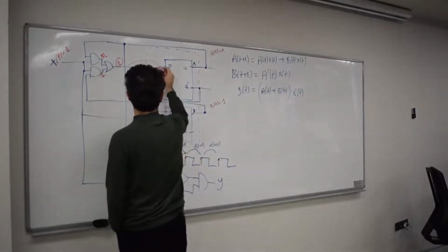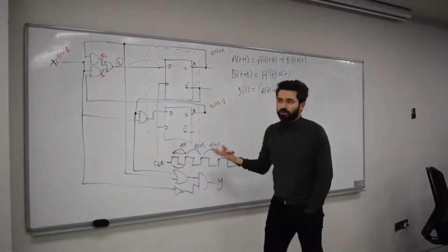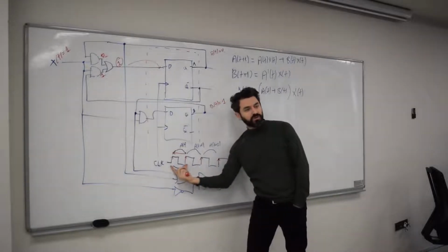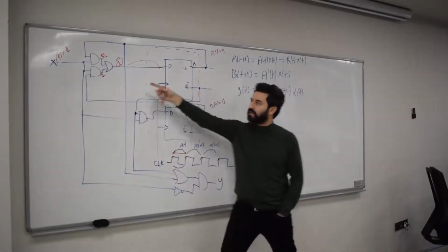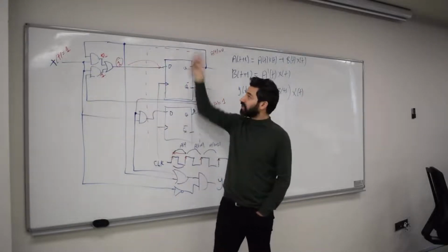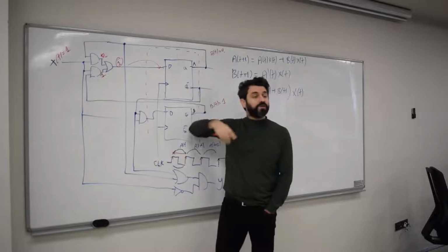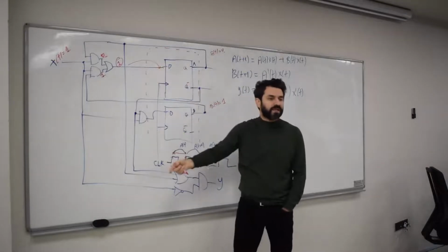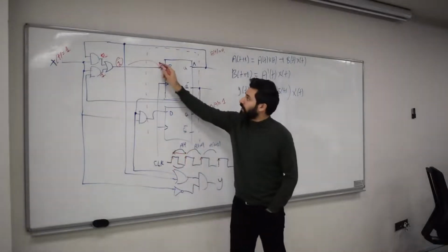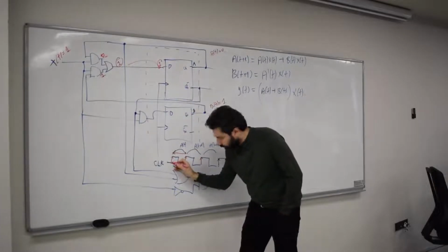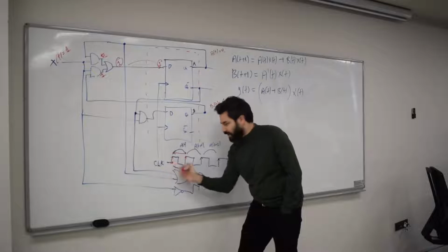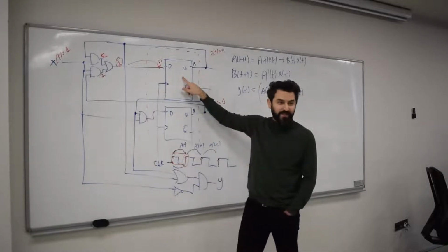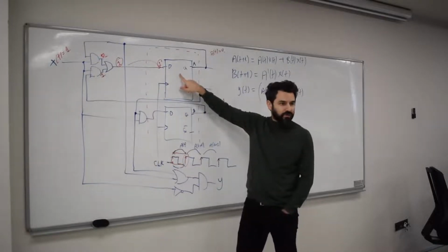This 1 will appear at the input of the circuit almost instantly, because it's a combinational circuit, remember. This period is chosen such that it's way bigger than the gate delays here. So it automatically creates a value here that would be your next state. However, you have to wait for the next clock cycle to assume this to be your next state. In other words, this one here is determined right here in a minuscule amount of time, and then you wait until you hit the next rising edge so that you can assume that value to be your next state.